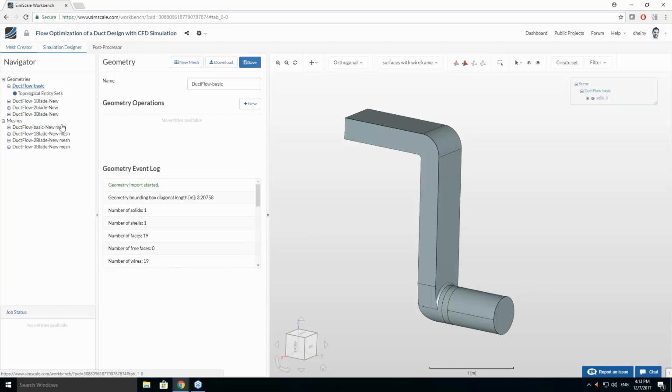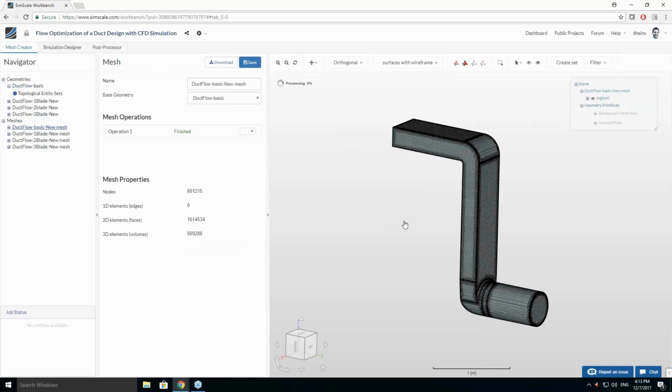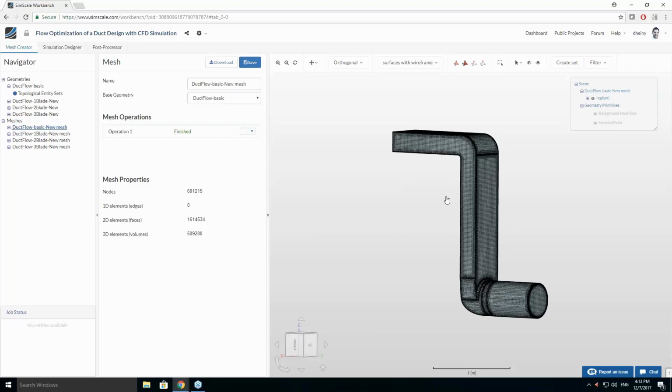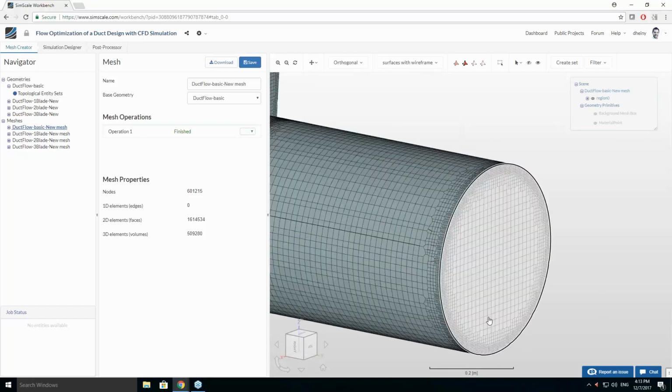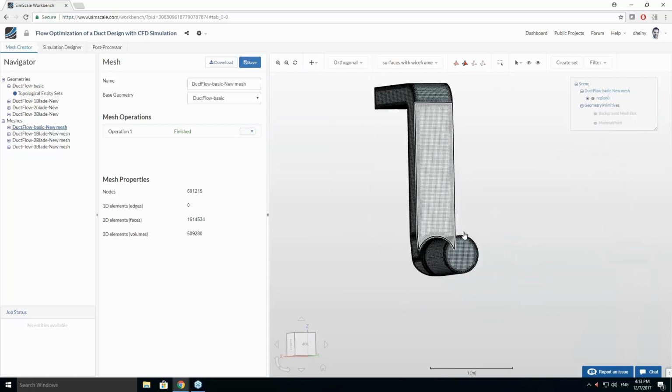And so if you've seen that last time, right? On SimScale, our philosophy of the product is you bring your CAD model and you leave with a design decision. So there's nothing else. You have everything in this web application to run high fidelity flow simulations. And so the first step is typically to create a computational mesh, which I've already created, right? So this is now basically many small cells that I use to discretize this duct.